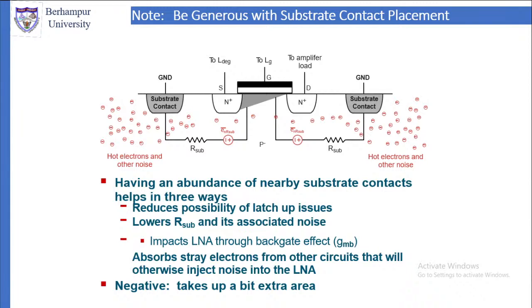First, it reduces the possibility of latch-up issues. Second, it lowers the substrate resistance and its associated noise.